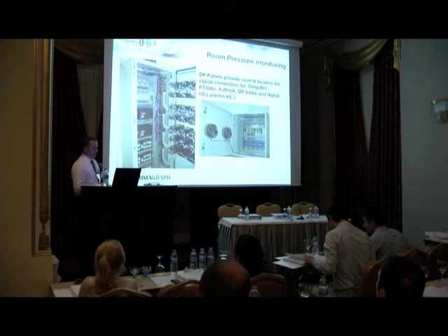So the system provides you with trends. You click the relevant alarm indicator to show the current trend. You can left click this point here and it'll display your alarm limits on the screen. So you might have a high limit and a low limit, particle counting obviously only high. And you can click the time base to say what period of time you want to look at the trend from. So you can put real time, historical, whenever you like.